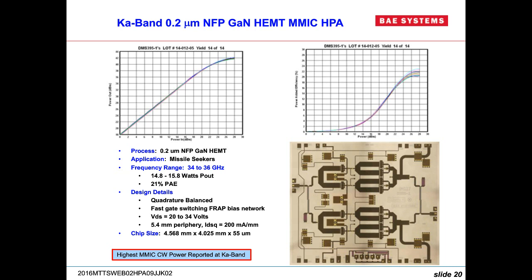Silicon is a mature technology based on the whole silicon world. Silicon carbide, originally you had problems with micropipes and defects and small wafer sizes, 2-inch, but year after year the basic starting material has improved, where now 6-inch is available with very small amounts of defects, and the cost has come down. So it still really comes down to a performance versus cost trade.